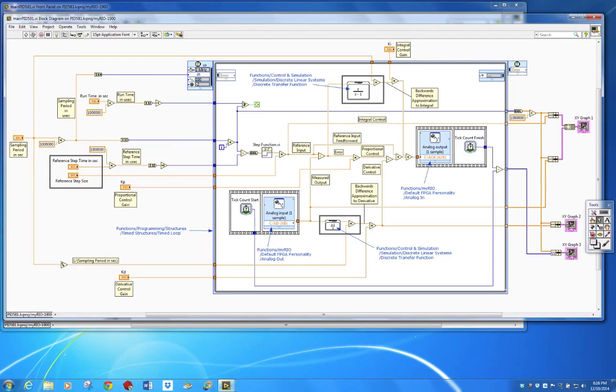5. Process the current error signal through both the proportional and the integral control signal paths. 6. Process the current measurement through the derivative control signal path. 7. Sum together the current values of all of the control signal components. This sum is then the current, also called the updated, control signal for the current sampling instant. And 8. Output the updated or current value of the control signal through the digital to analog converter so that it can affect the analog plant.